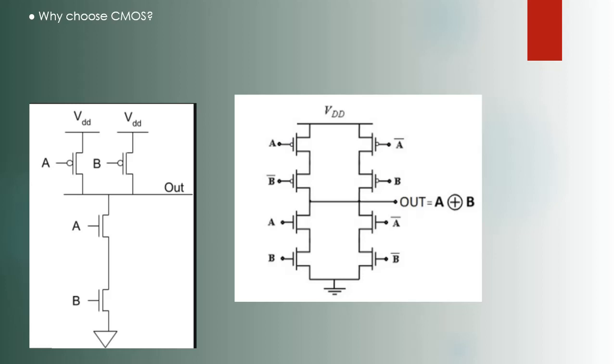So why choose CMOS? In the CMOS device, one of the transistors is always off, and hence the device draws power only during switching or toggling between states. Thus, the device is very power efficient. The power dissipated is proportional to the frequency of toggling. Another advantage of a CMOS device is its high noise immunity. Presented below are a few gates implemented using CMOS transistors.